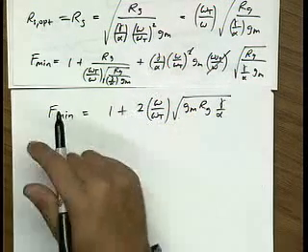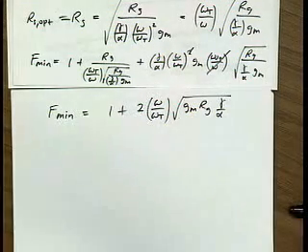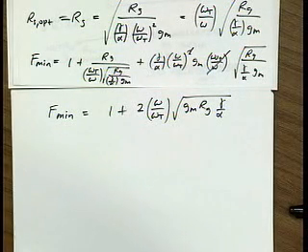Yes, there's a question. You're solving for RS opt. Isn't F taken with respect to RS equal to 50 ohms? So if you're doing RS opt, then what? How does that work with the noise figure?